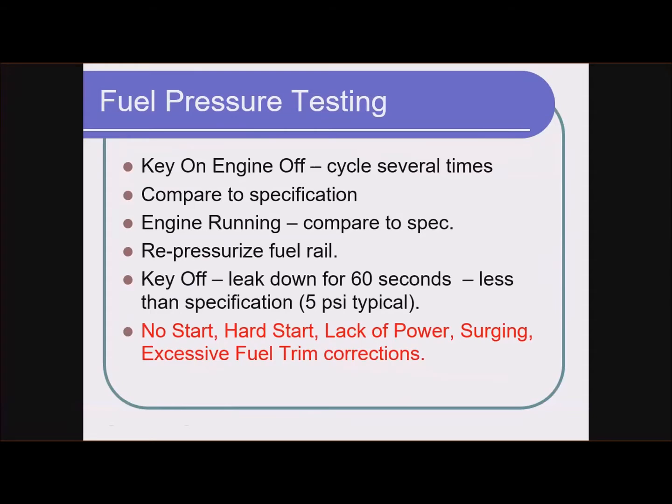But the car would do okay idling. It would do okay driving around town. It was just when you tried to go fast. So that lack of power could definitely be caused by a fuel pressure concern. Should be pretty obvious as soon as you put a gauge on and start it up.